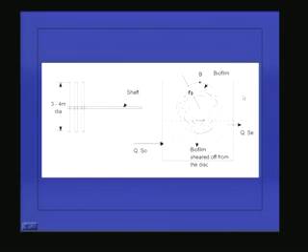This is the unit, and the wastewater will be there up to this level. That means around 40% of the disc will be immersed in the wastewater. A flow rate of Q is coming in, and S0 is the initial BOD of the wastewater, and this is the disc. This is the center of the disc and this much portion will be immersed in the wastewater.